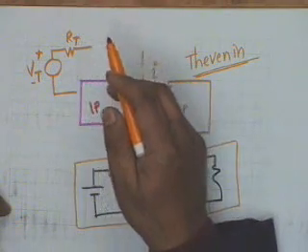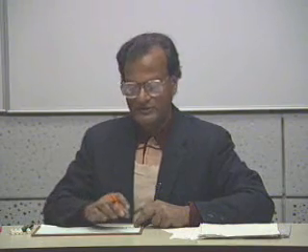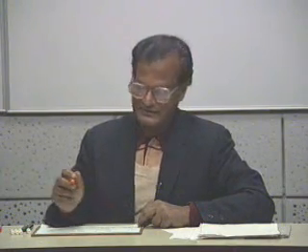It's an arbitrary one port. An arbitrary connection of a one port to another one port. In so far as the load current is concerned, the one port can be replaced by an equivalent voltage source in series with an equivalent resistance. The values of Vt and Rt we shall consider on Friday.